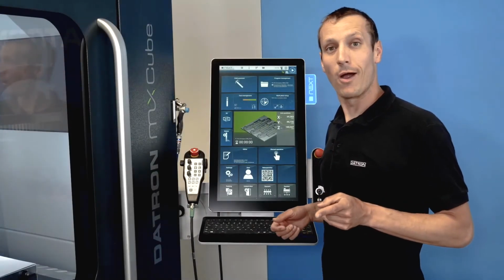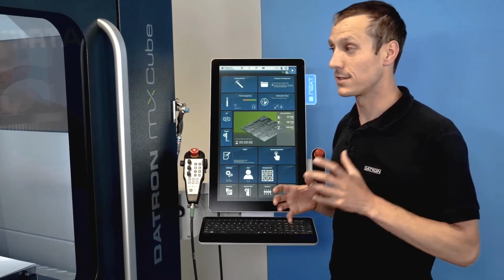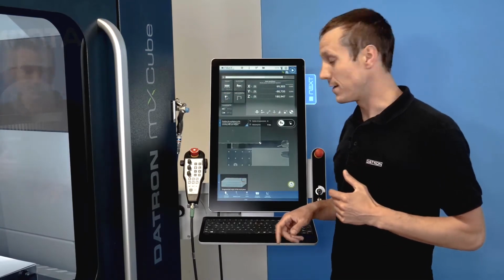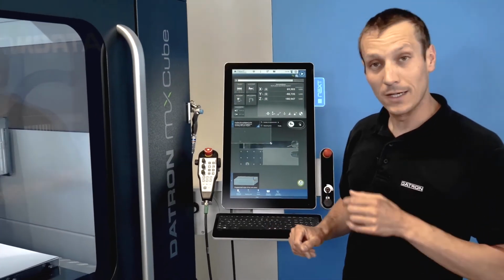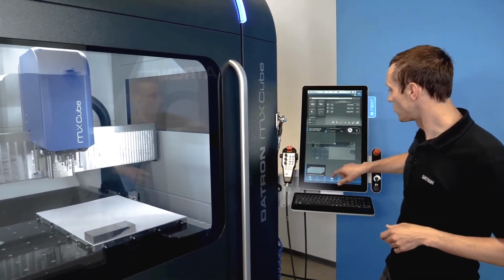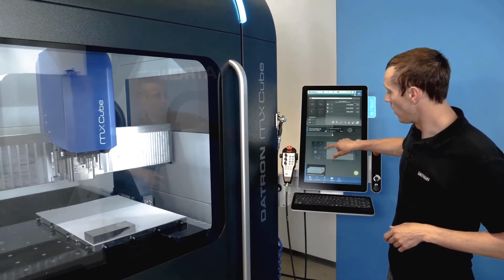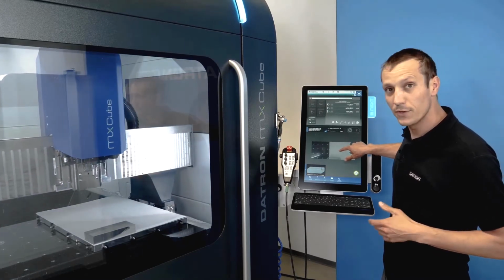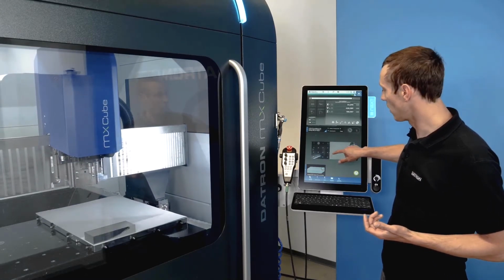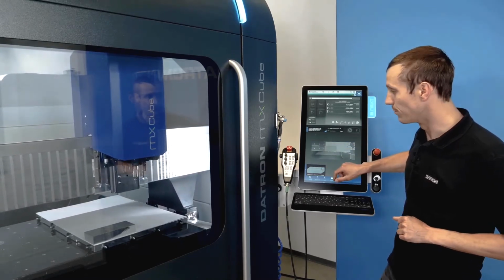The most interesting and exciting part, though, is to work with a camera system in order to set up your origin. Because what we do have is, on the Z-axis, there is a little camera which gives us a live view of the machining area. When I go to set up workpiece and I get this live view, I can just swipe over my screen and move the entire gantry with it. So I can basically drive my machine around just by dragging my finger over the screen.